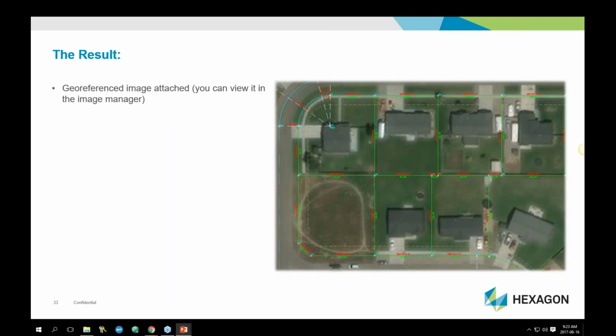And then the result would be a background image for your survey data. So it will be either the aerial, which I've shown here, or the Bing road maps. And if you're wondering about the quality of the image, you can just go on the Bing website, and that will show you the quality and resolution of the imagery in your area.